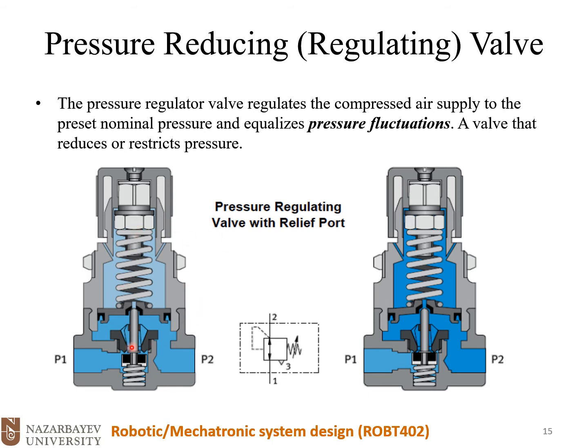When the pressure is high, it pushes the spring back, which increases the volume in this chamber and automatically drops the air pressure.